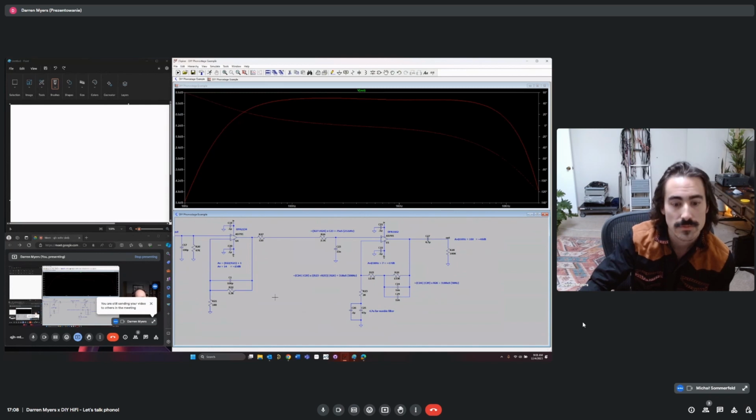Yeah, and also speaking of the resistors around the opamps, we can't make them too small because we'll overload the opamp's output. Yeah, absolutely. Great point as well. So you might say, well, let's just make this 1 ohm and make this like 130 ohms. You can't do that because the output of this amplifier is seeing the impedance of R22 plus R21.